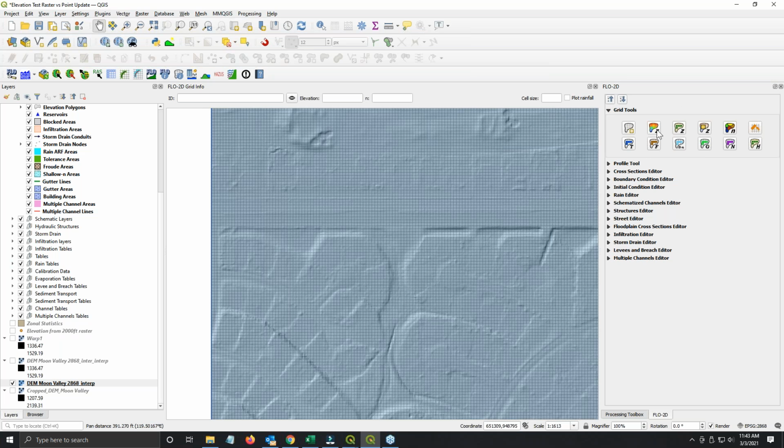But when you're applying these two tools to a regular project where your data is not perfectly aligned to your grid and you're not sampling exactly the same data, they're not going to give the same results for a grid based off 2 different data sets because of the weighted average. So the raster is a weighted average and the points is not. So that's why they have different results. I just wanted you to understand how these tools work and what they do.